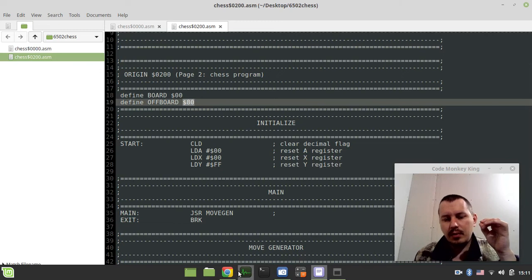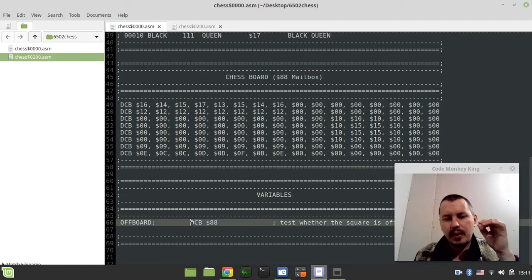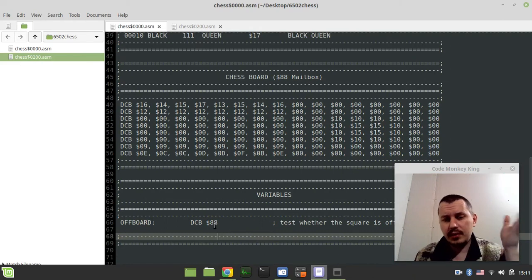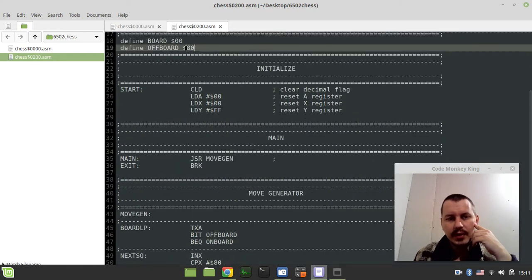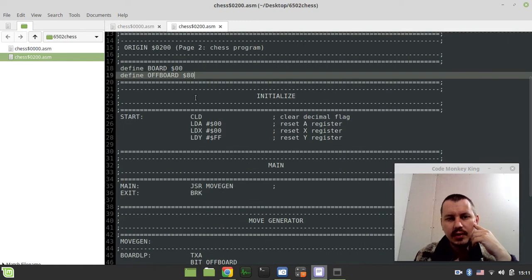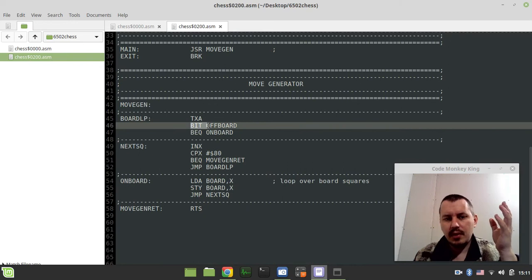And if we have a look again at the hex dump, what is there? We have the 88 being defined there. So this concept of hexadecimal 88, that's the same as what we've been doing in C and JavaScript. So BIT bitwise ANDs the accumulator with this value, but it doesn't change the accumulator, because the BIT operation doesn't change the value of the accumulator. If this was the AND opcode, in that case it would be changing the accumulator. But since it's just a BIT, it doesn't.